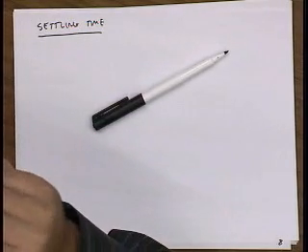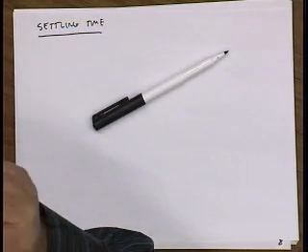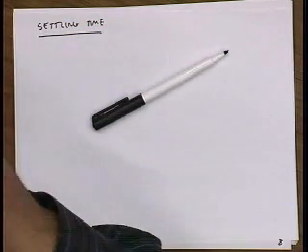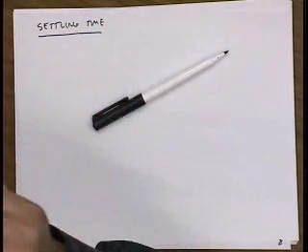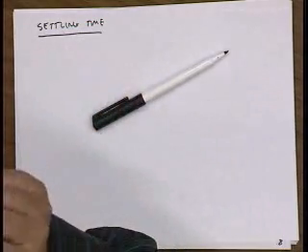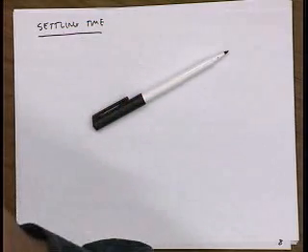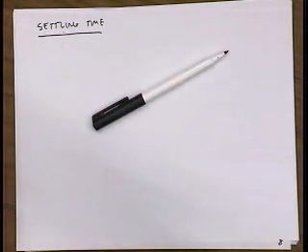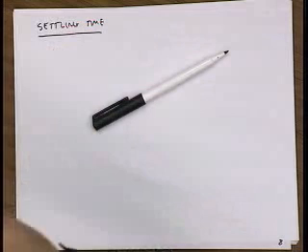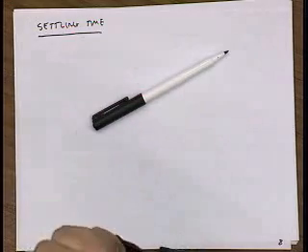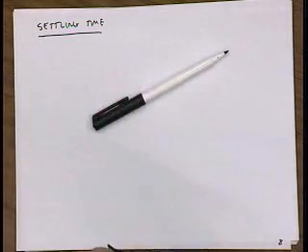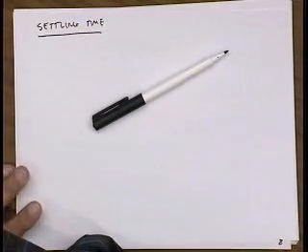If the sink of that information is the human eye, I might say, well, you know, I've done some experiments and I know the human eye is about 1%, you know, sensitivity about 1%. If the image varies around that, no one's going to even tell, right? So if I'm designing an oscilloscope and there's a trace on that oscilloscope, I might say, okay, the accuracy of the function I'm trying to do here, amplification, should be about 1%. Might actually be much more, for the human eye, it might even be 5%, right?